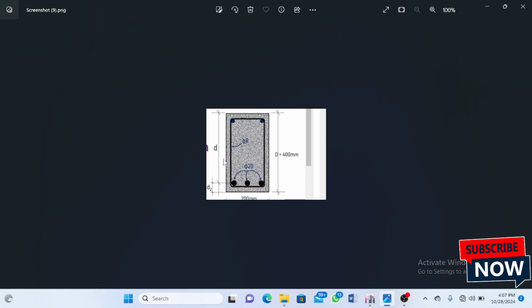So here, let's say we have a cover of 25 mm and we have a stirrup of 8 mm, or let's say 10 mm. Let's stick with 10 mm. And this is a reinforced bar, maybe 16 mm. So the distance from here is the cover plus the diameter of the stirrup plus half of the bar diameter.